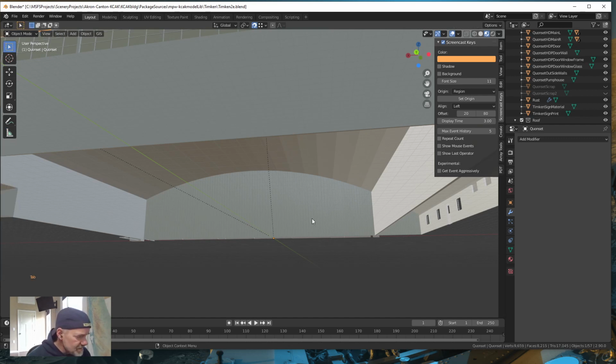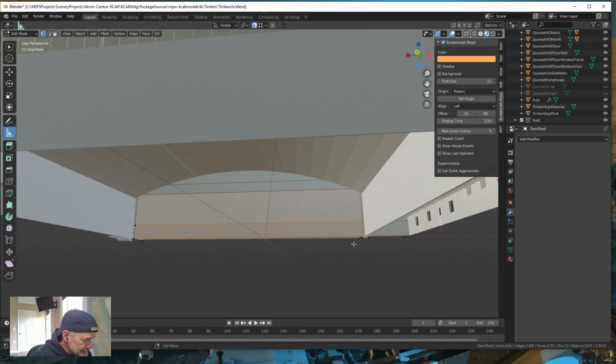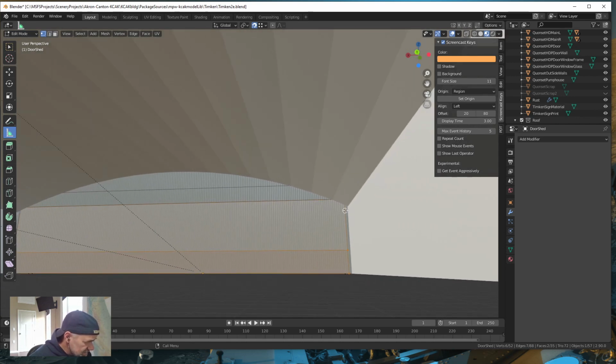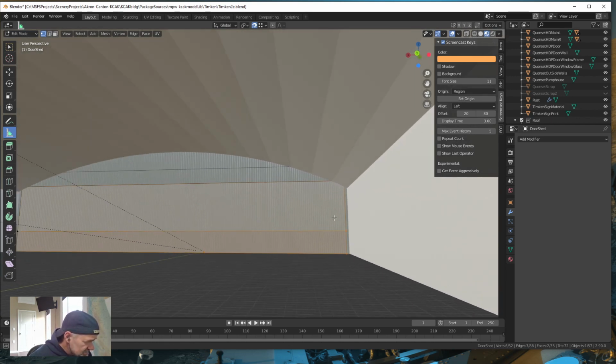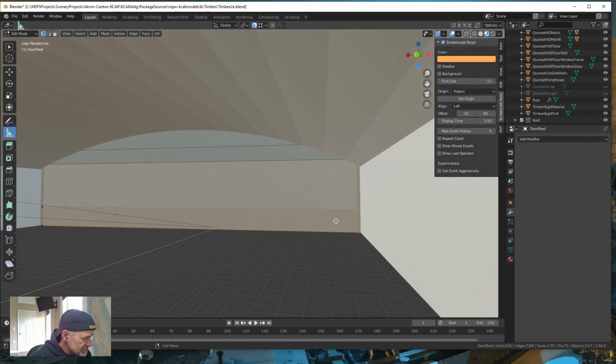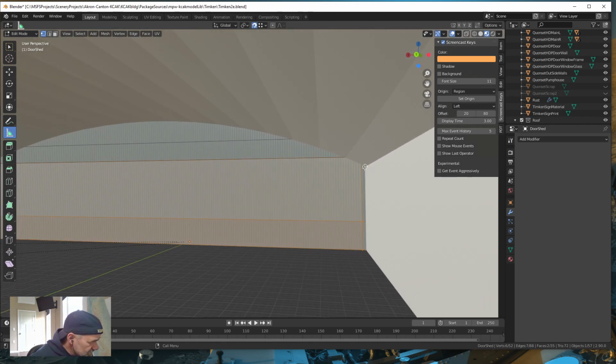Okay, so get out of edit mode, select our door shed, tab into edit mode, and let's add from this point right here down 1.15475 feet. So we need a reference line that is the top of this wall.